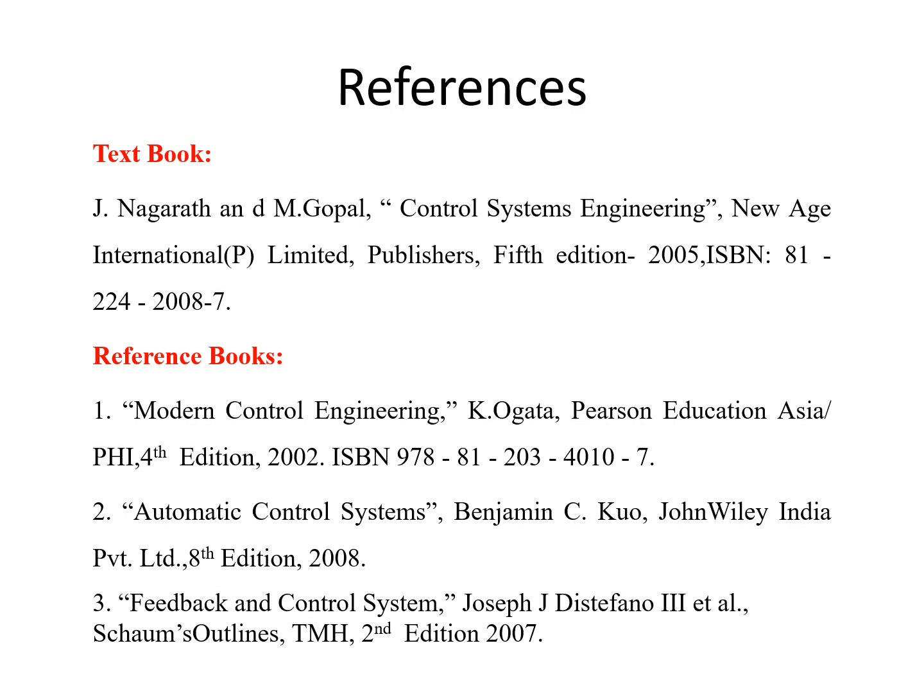So in today's session we have discussed standard test signals. The important standard signals used for the time domain analysis of the system are the impulse signal, step signal, velocity signal, which is also called the ramp signal, and acceleration signal, which is the parabolic signal. And we have learned how to find the Laplace transform for all these standard test signals.